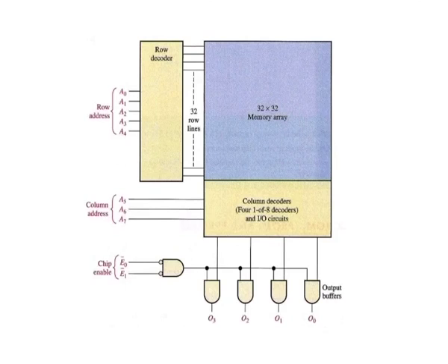The result of this structure is that when an 8-bit address code A0 through A7 is applied, a 4-bit data word appears on the data output when the chip enable lines are low to enable the output buffers. This type of internal organization or architecture is typical of IC ROMs of various capacities.